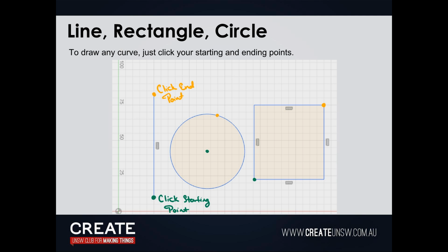Line. You can set the angle you want. So for example, if I want a 70 mil line at 45 degrees, just hit tab and you can go into that and you're done. It'll even show you the angle. So if I want to change the angle, maybe I want it at 85 degrees, like that. Very simple. Now for this purpose, we'll just have it at 90 degrees. Click the point, draw a starting point, draw an end point. Rectangle, circle, we'll do that now.